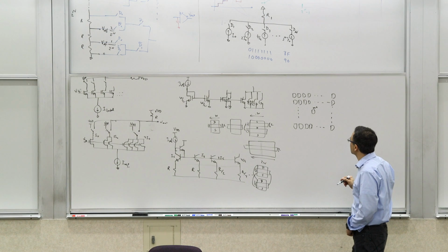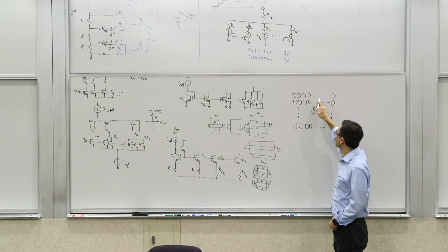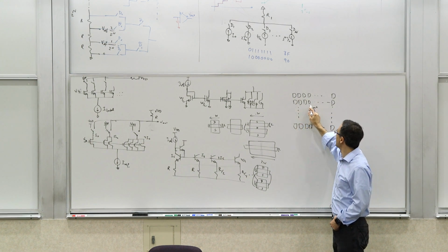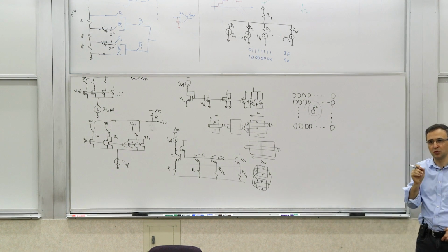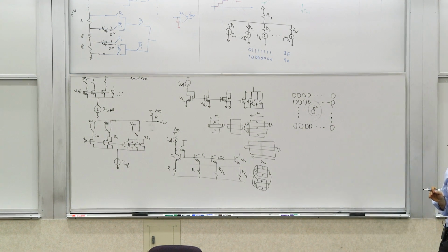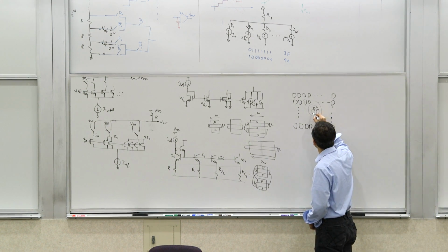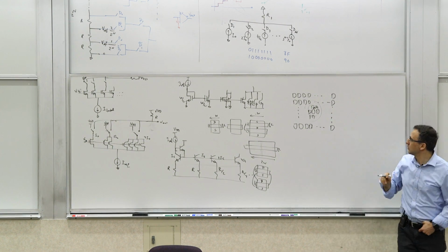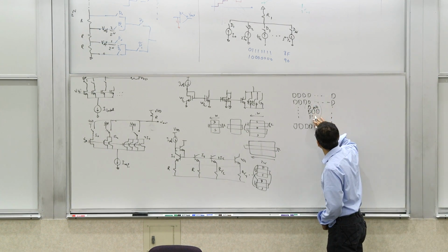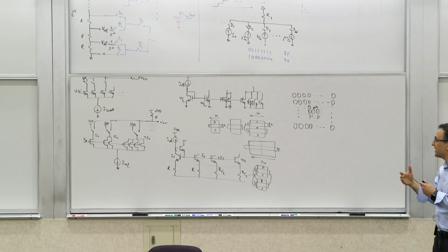Now, what else do you do? You can arrange them in different configurations so that you minimize the gradient effects, going around this in certain ways and connecting them that way. You may not be able to do it perfectly, but you can try to make arrangements that are conducive to that. For example, the next 2 could be here and there, and the next 4 could be here, there, and so on. Or other arrangements, you may put them here in the corners, and then the next ones. You can arrange them in a symmetrical fashion.